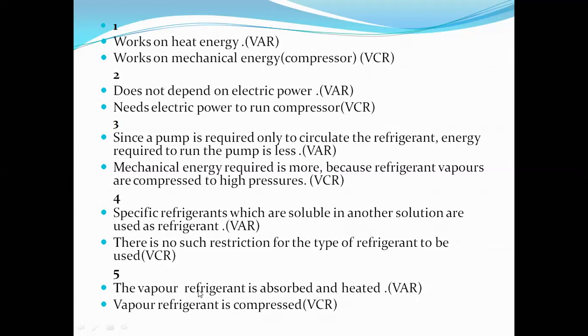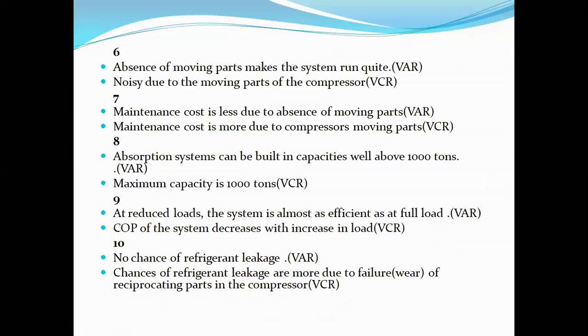The vapor refrigerant is absorbed and heated in the heat exchanger, whereas we don't have a heat exchanger in VCR. Instead of absorption, we have compression; vapor refrigerant is just compressed in case of VCR. And the sixth difference is that,